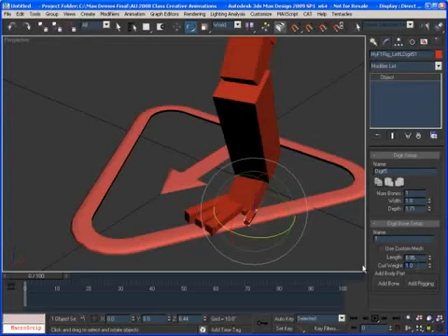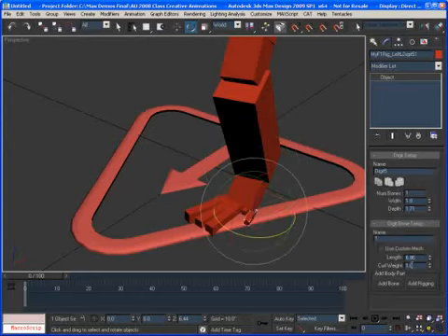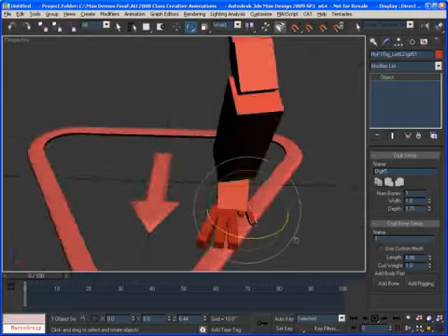The curl weight is going to be very important, because when you're on the palm here and animating, there's a curl setting that you can play with, and the curl will affect all of the toes, and you can then adjust the curl for a single toe as well. But basically, for the overall curl, you can adjust the weight of that, how much this toe will be affected by the overall curl. It's kind of a multiplier of that overall curl. So you can define the behavior of the toes by adjusting that curl weight here. So we've got the toes done.